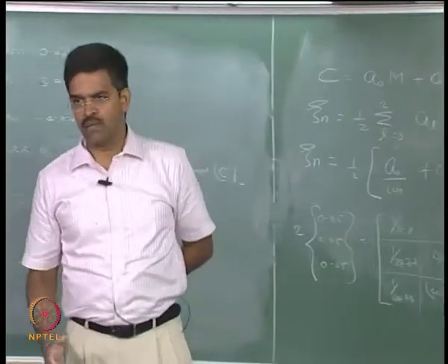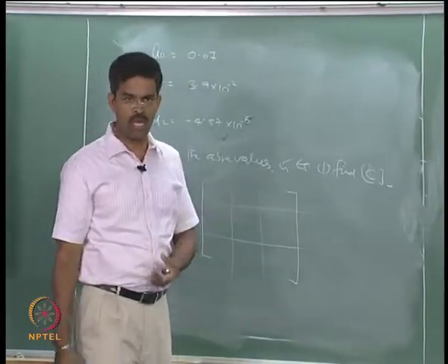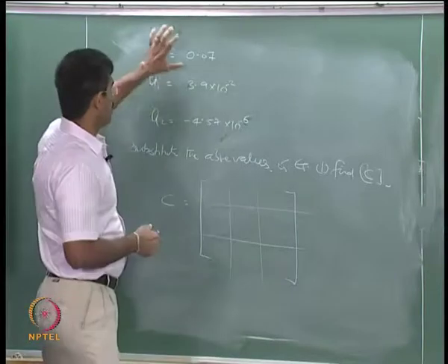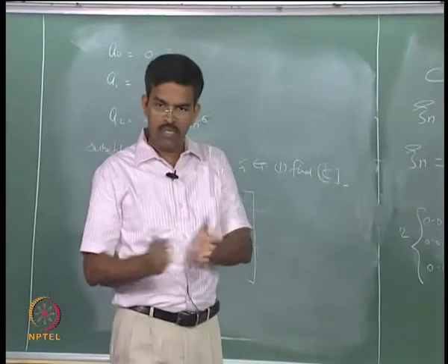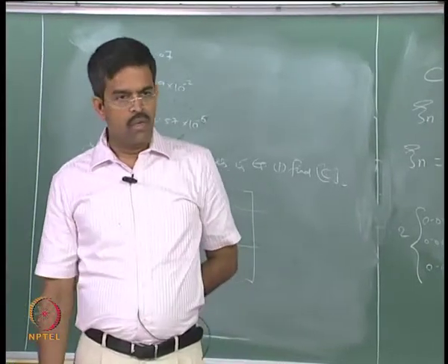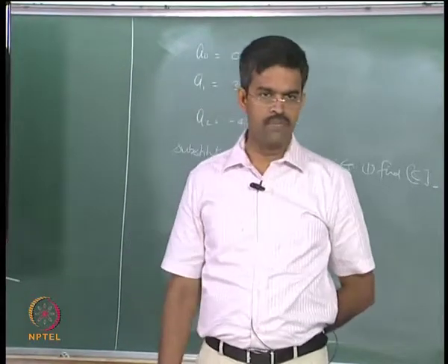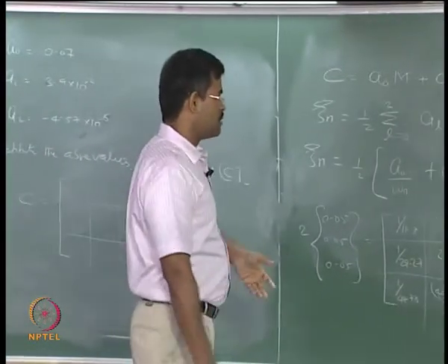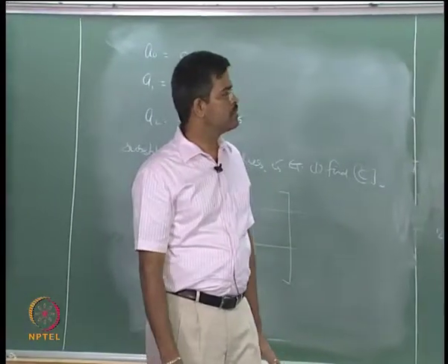Of course, we cannot compare the damping matrix obtained from A0m, the damping matrix obtained from A1k, the one from A0m plus A1k, and the one obtained from A0, A1, A2 with k, m, k inverse etc. We cannot compare them, they are all different formats because they include different contributions of modal frequencies or modal damping ratios in your calculation. So, it cannot be compared. Which one you use depends on the justification or the decision of the analyst. So, that is where we stop here.